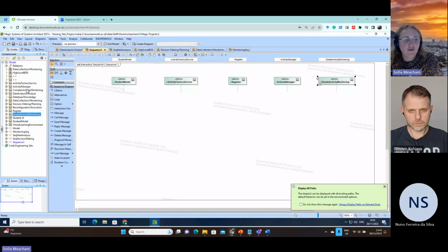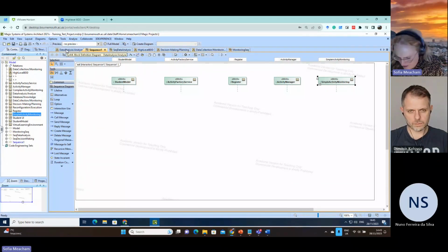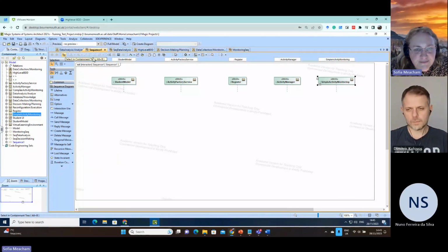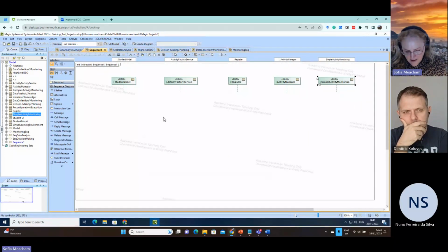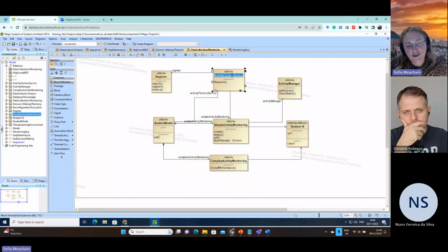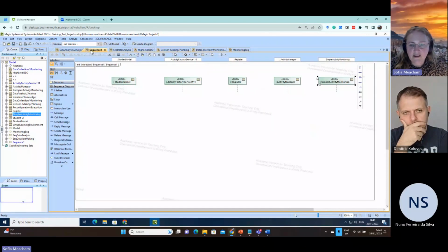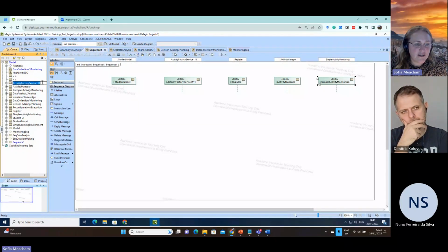So that way, by dragging from the model elements and putting them in the diagram, you automatically connect what you had in your block diagram, which was the monitoring one. Yes, so you connect parts of it with your sequence diagram. I am here in this sequence diagram. And if for any reason you are in your collection here and you want to just change the name, then automatically it changes here as well. And that is the point that model-based engineering can be helpful. And if you change the name in here as well, then it will change it everywhere too.